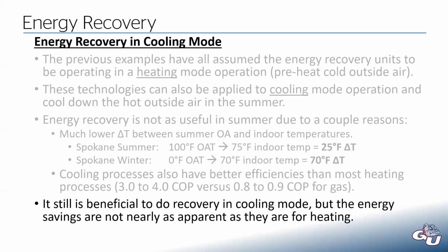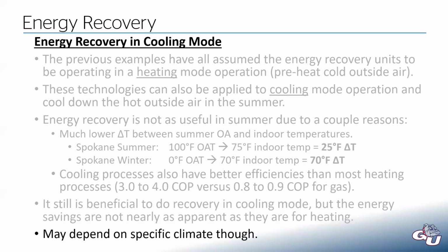Say if you were in Arizona or Florida, where it's pretty much cooling mode year round, you probably wouldn't install an ERV just for cooling. There might be some examples. It could depend on the specific climate, but generally speaking, most of the benefit here is on the heating side.